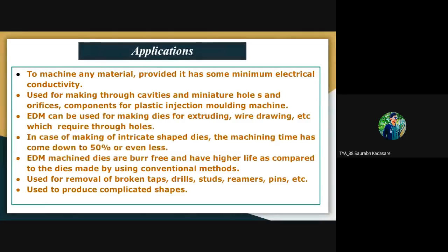Again in this EDM process no mechanical forces act as in our conventional machining. So hence this process can be employed to machine thin and fragile components, okay, without any danger of damage due to such force. Okay, so these are the applications of this EDM process.